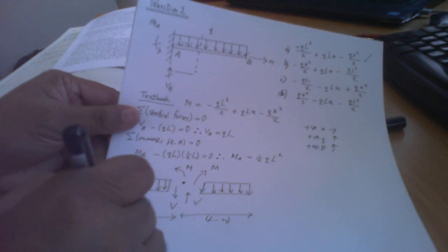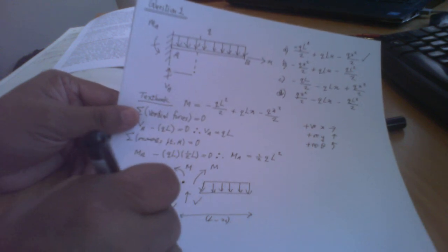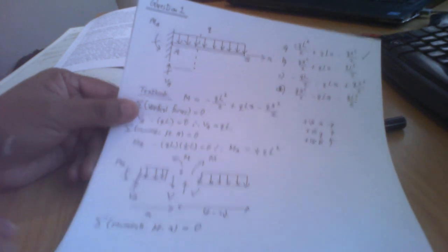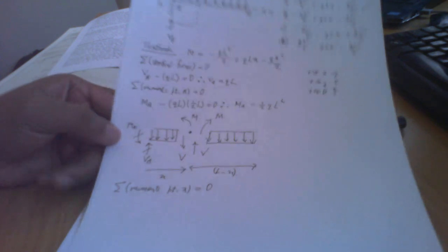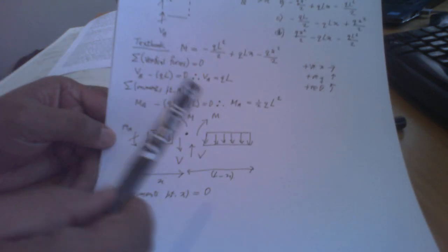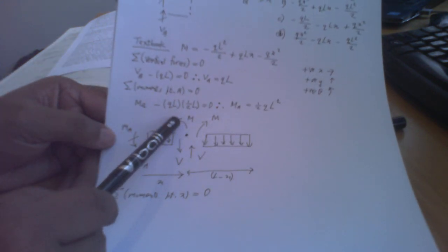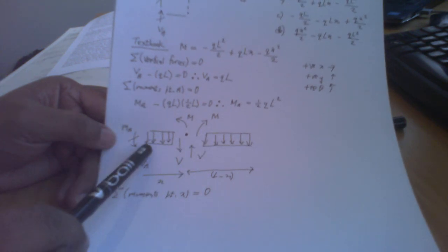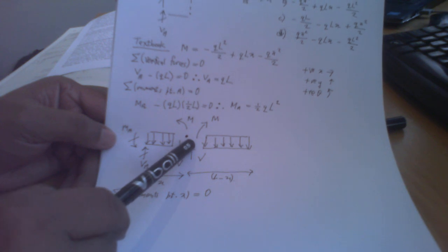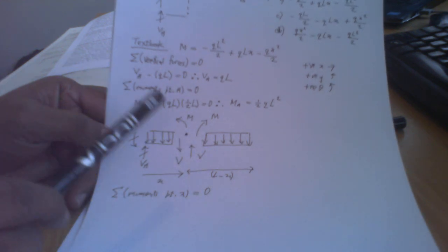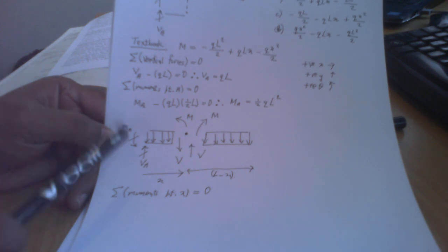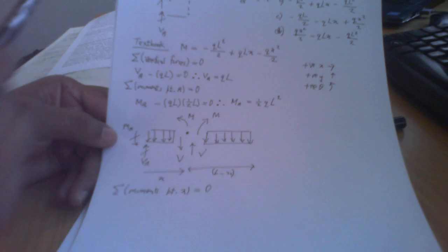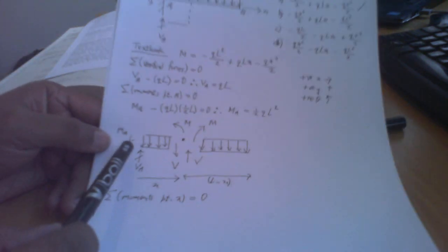So we would take equilibrium of moments, sum of moments at point x is equal to 0. Isolate what is the moments acting. There is the moment within the beam. The shear force doesn't contribute. The reaction force causes a clockwise bending moment, which is in opposite direction to the positive bending moment. Therefore this would be negative. And the reaction moment at point A would be present.